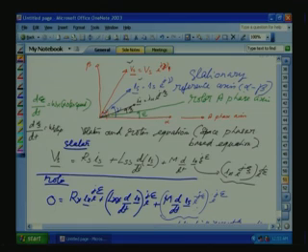Now, the whole voltage term we are transferring to the stator by e^(jε). So, the epsilon outside the bracket will not come into the d/dt, because the voltage term we are transferring to some other axis, that is all. Now, as I told, we are defining the stator voltage and current with respect to a common reference phase axis, that is alpha beta. That alpha is placed along the A phase axis. This is also called the stationary reference frame axis.